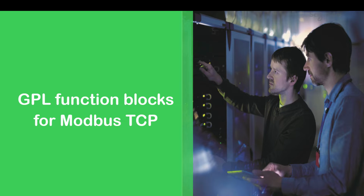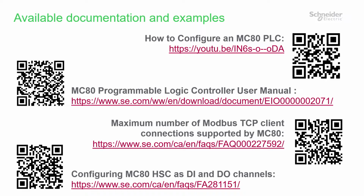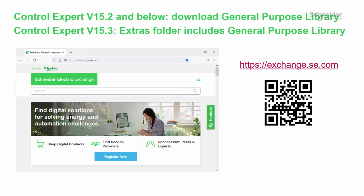And now we will configure the MC80 controller to use the GPL communication function blocks for Modbus TCP explicit messaging. Let's start with the main links for documentation, FAQs, and a great training video available on YouTube, as well as the link to download the Control Expert General Purpose Library version 2 from the Exchange portal.